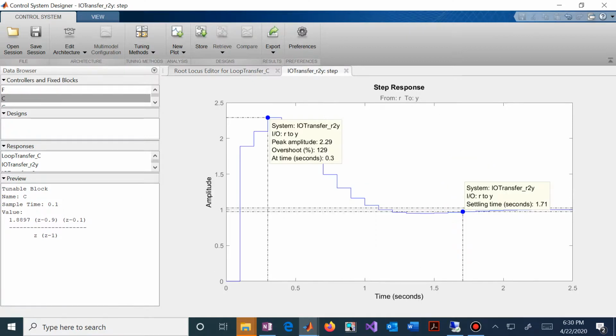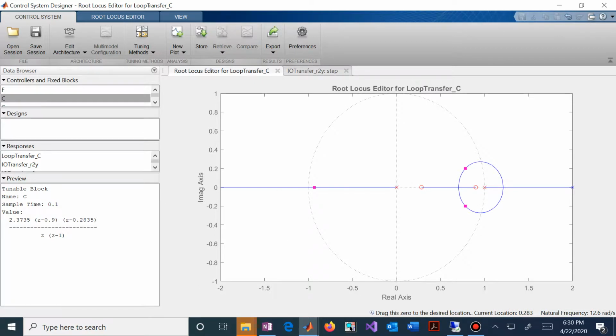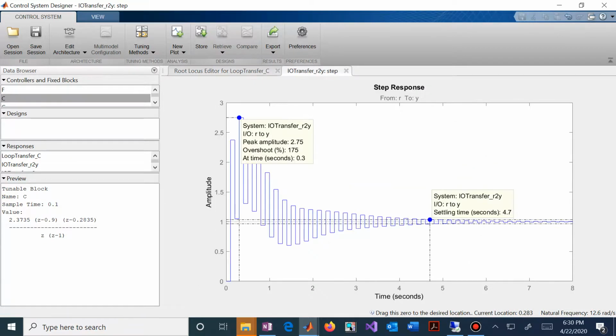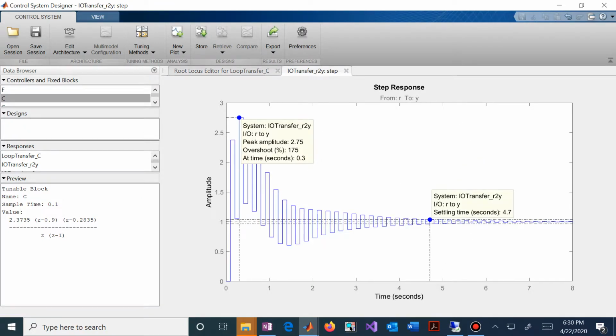The input-output behavior is what we were expecting for those locations. And now if you said, well, maybe if I change this zero, what will that do? Well, now you can see what happens. That now pushed that zero almost outside the unit circle, and that's what's giving rise to this terrible ringing in your response.